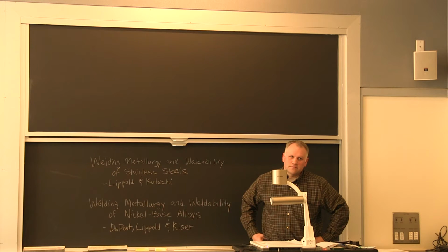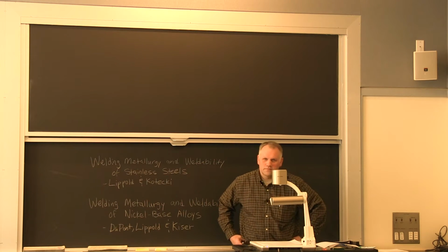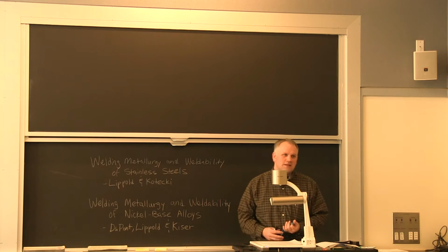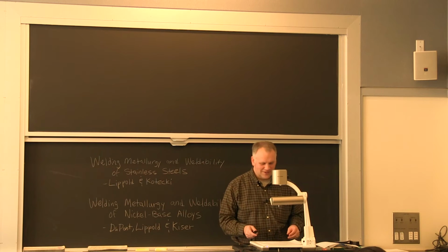Some things are plenty ductile at low temperature. Silly putty is a good example. I can take silly putty and stretch it, stretch it, stretch it. Good ductility. If I pull it really quick, it snaps. That's low toughness. So there is a difference, but many people equate them. Okay, but there is a difference. I like the silly putty example. That's a good one.